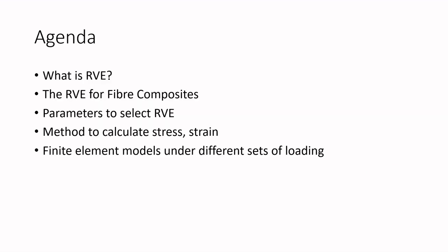In this short video I will touch on what is RVE and how it looks in the context of fiber composites, and the parameters which affect the RVE. And then in the end there will be three finite element simulations for different sets of loading to calculate the mechanical properties of fiber composites.